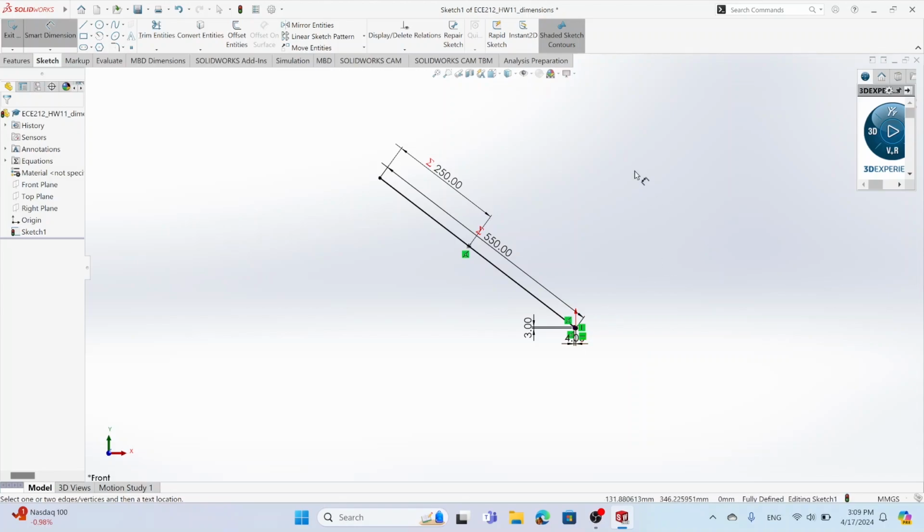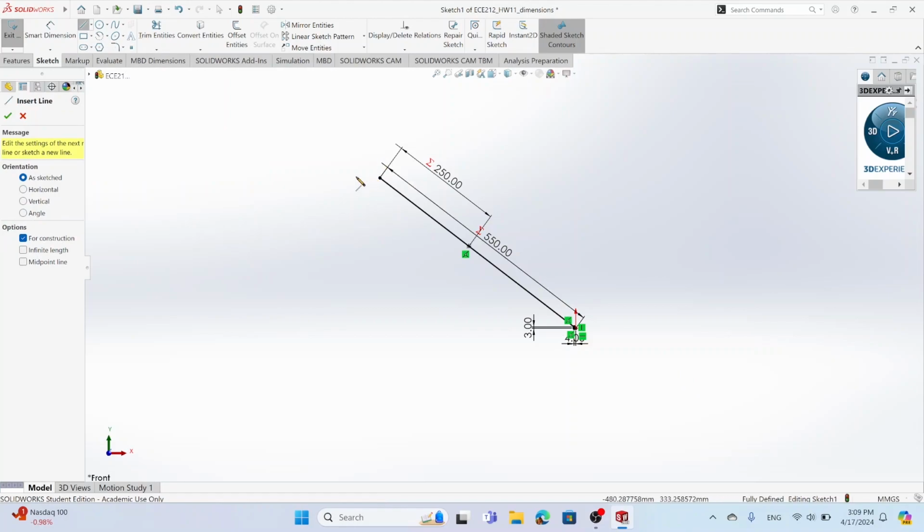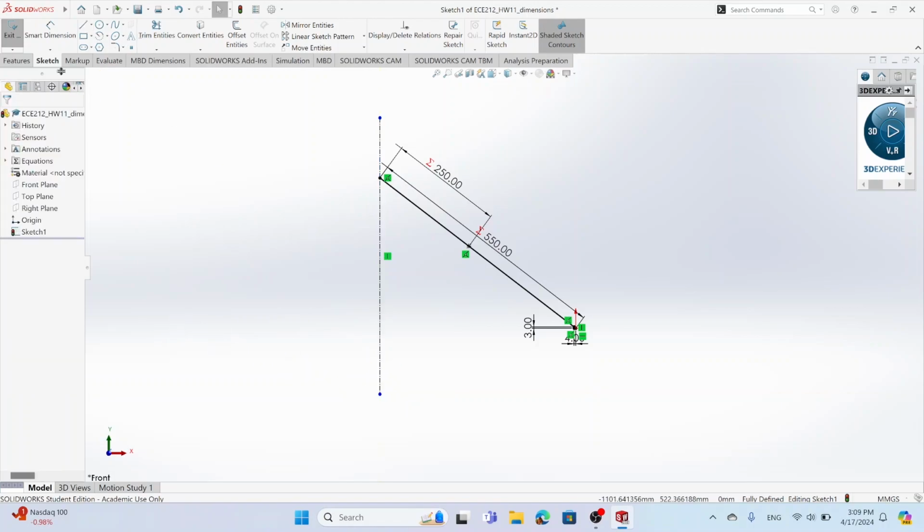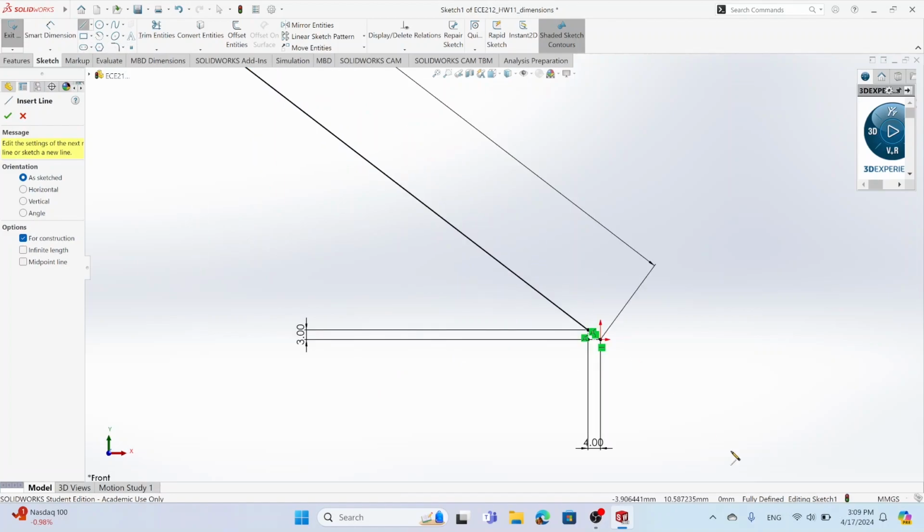Okay. Let's say we want to find right away the AC. I will use a center line. We know that VA is up and down, and VB is right and left. So I draw a perpendicular line to VB. Here we go, vertical. Match it, make sure that it is vertical there. And I draw a horizontal center line from that point on the bottom.